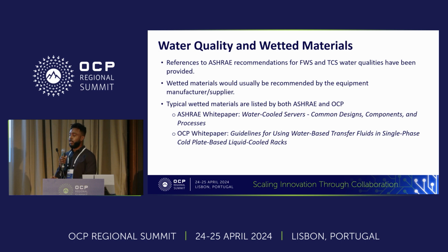In terms of the typical wetted materials, they're listed in the ASHRAE white paper that's listed there for water-cooled servers, the common designs, components, and processes. And then OCP put out 2 white papers under the cold plate group that covered the water quality and wetted materials for propylene glycol and treated water. So just to be aware that we added those references so that people who are looking at the door heat exchanger spec are aware.